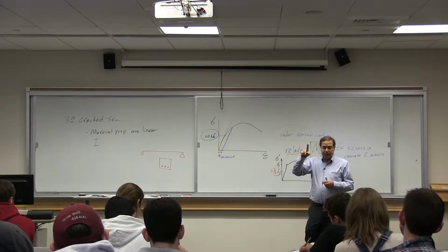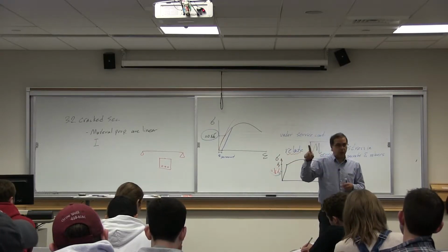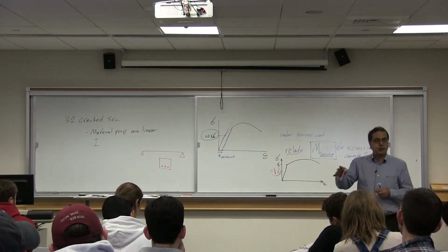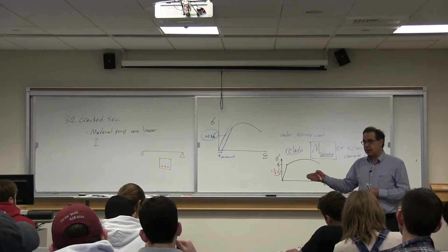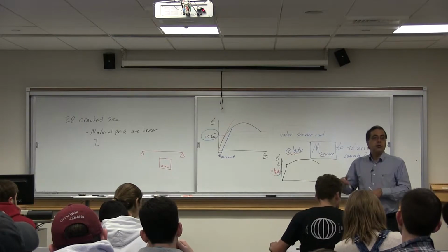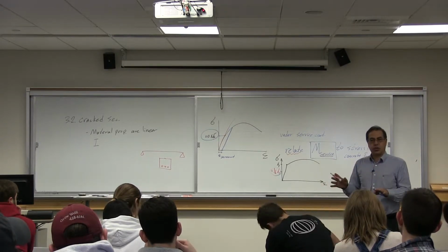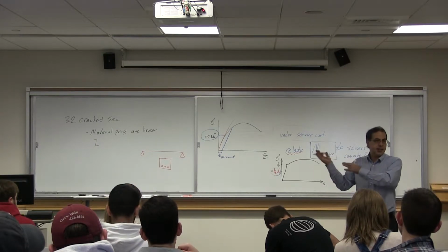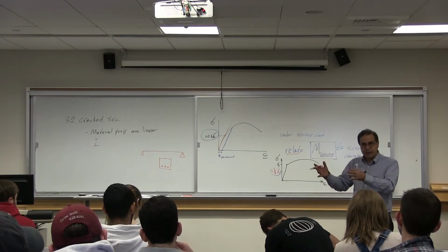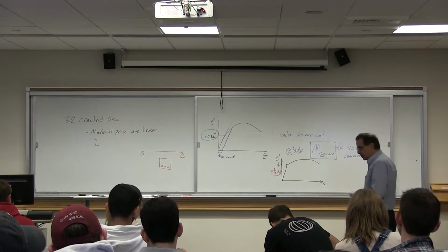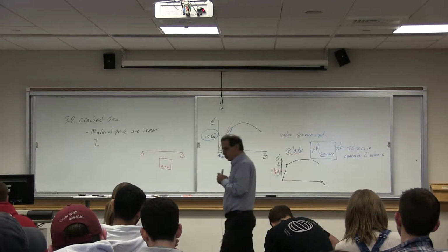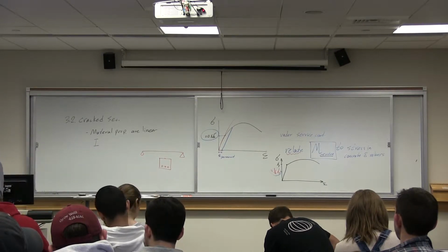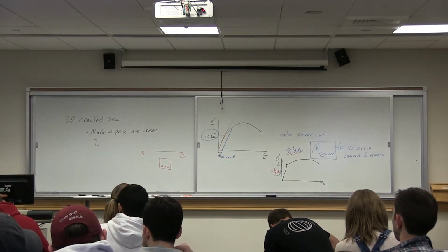Is that the heaviest truck that should pass over the bridge? No. That's the truck that can pass over the bridge on a daily basis. A question could be, what is the absolute heaviest truck that can pass over? That's a different question. We can answer that later. Okay, at this time we say, what's the amount of load you can apply to that structure every day? That could be equally applied to a floor system.